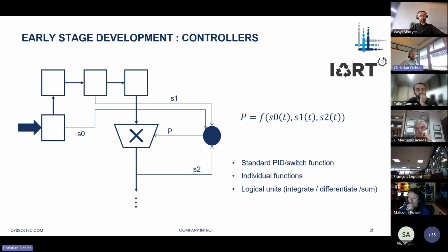Actually, our idea was, yes, to tune. By loop tuning, you mean to parameterize your controller function, right? Yeah, right. That's the idea, to optimize your controller. I mean, when you have a dynamic process, you can control several units and again decrease probably the startup time, etc. And of course you can test different functions. Right. So essentially, you're trying to minimize the error that you get because of any variable change in the actual process.